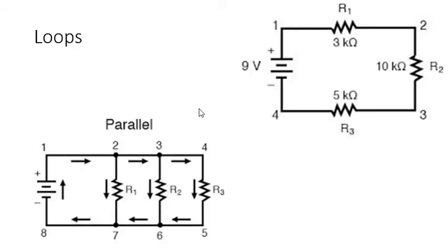And we're going to do it with the same circuits that we started with before. So the parallel one's already labeled assuming positive flow, but we'll get back to that in a second. So we are going to say that positive flow is the way we're going to look at it. From here on out, not just these two circuits, every circuit, we are going to say that flow leaves the positive side of the battery and enters the negative. And again, opposite of what's really happening. But that's just the way everyone does it, right? Everyone says it comes out the positive, goes into the negative.